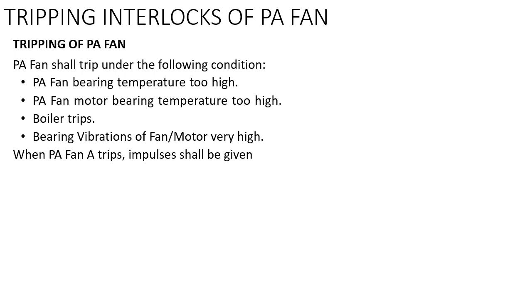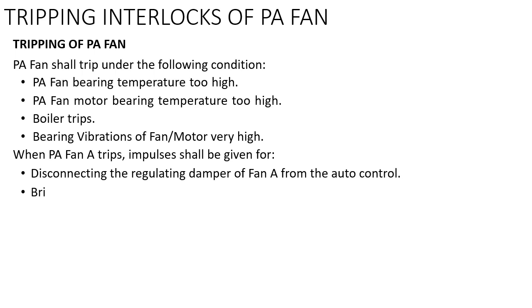Now if the boiler trips, the PA fans will trip. Also if bearing vibrations of fan and motor are very high. If they are high you can manually trip them, or if they are very high the tripping may be provided.